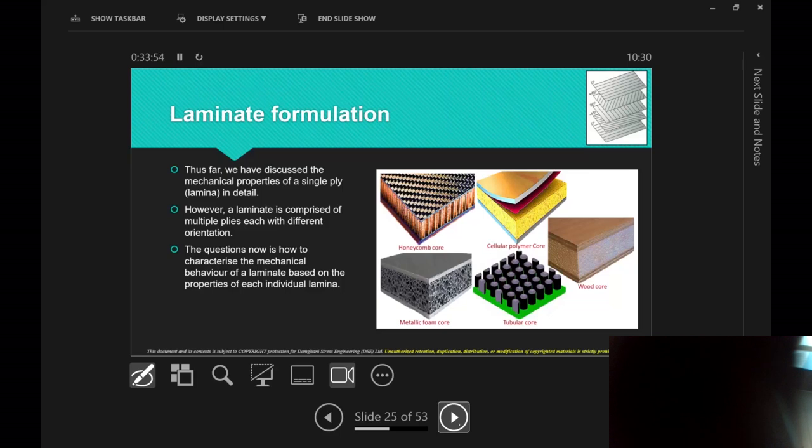You might say that. But believe you me, if you don't have that, and you've got a lot of, let's say, bolts and fasteners, you will get high stress concentration and the whole thing breaks up. Having a strong material is good, but at the same time you have to compromise on stress concentrations and delamination. If you've got plies of the same orientation stacked up more than 3 times, your laminate delaminates basically, which is not good. So it's essential to have these 45s. They're really good plies anyway.